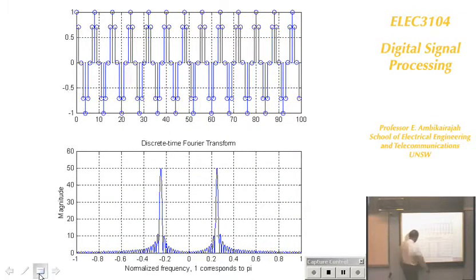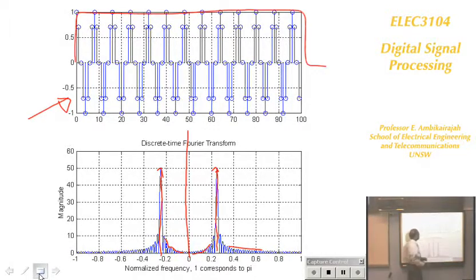This is another signal, a cosine waveform in MATLAB, and if you take the discrete time Fourier transform, whatever frequency you work out, that's your center point. You get your signal there at that frequency, and symmetrically there as well. You will have all these ripples because you're taking a rectangular window, because you're grouping a signal like from there to there. As soon as you group a signal, this rectangular window effect comes in. That causes all these problems.